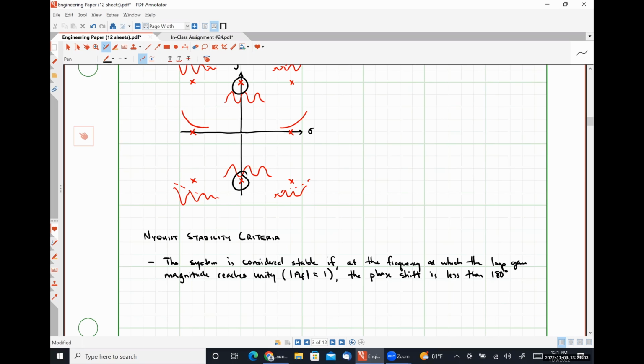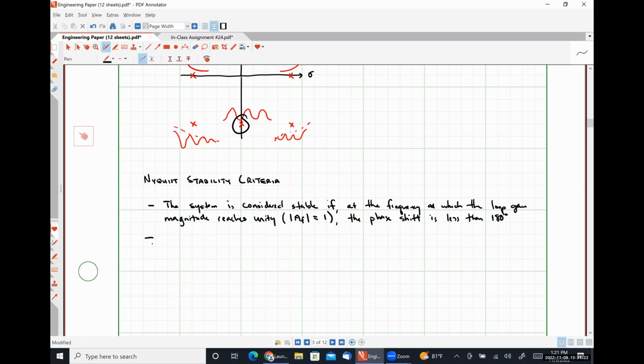So effectively, we want either the gain margin or the phase margin, and it's literally impossible to have them not be positive at the same time or not be negative at the same time. So as long as one of these meets the criteria, both of them have to meet the criteria, okay? So quantify the stability of our system. Put this down.